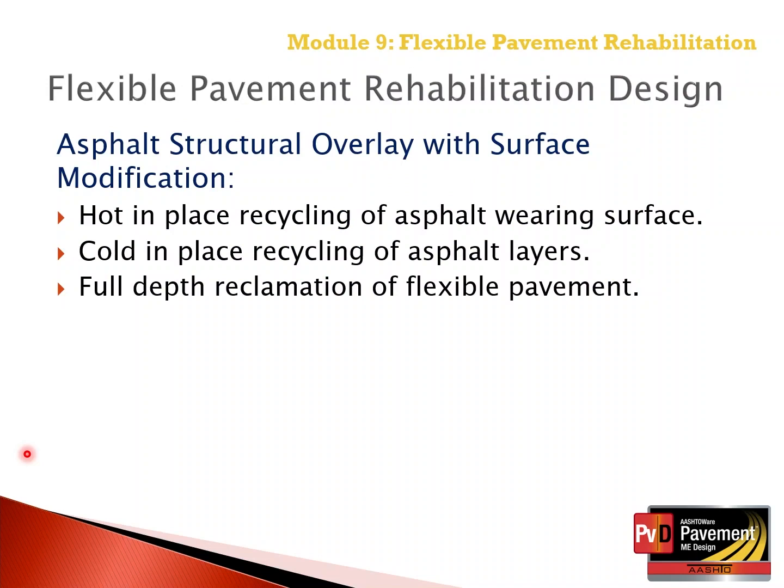So as mentioned earlier within this module, asphalt structural overlay with surface modifications are an option: hot in place recycling of the asphalt wearing surface, cold in place recycling of the asphalt layers, as well as full depth reclamation of the flexible pavement. All of these three surface modification methods are not specifically included or simulated in the Pavement ME design software.